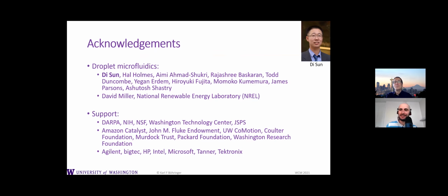Yeah, so the current demo systems that we have are not really designed for efficiency. We have a vibration platform. Remember, the frequencies are pretty low, somewhere between 40 and 80 hertz typically. So piezos are maybe not the most efficient way to achieve that, but we currently use just a regular linear electromagnetic motor to do that.